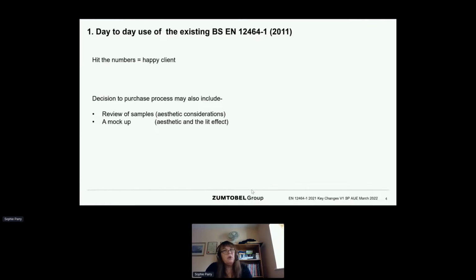You're not actually going to work under this light, but you are subjecting other people to maybe working under it for up to 8 hours a day in a study space or an office. So let's just stop and think about this, because this could be an emotional decision you're making based on the fact that that luminaire is the brightest and sparkliest one on offer, and your attention has been drawn to it on that basis.